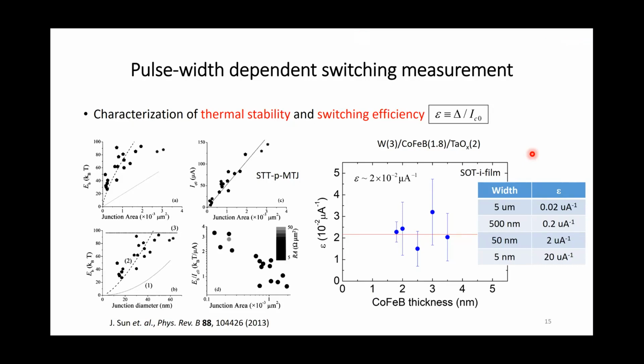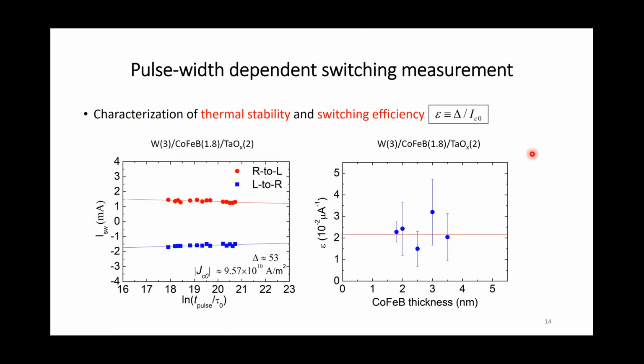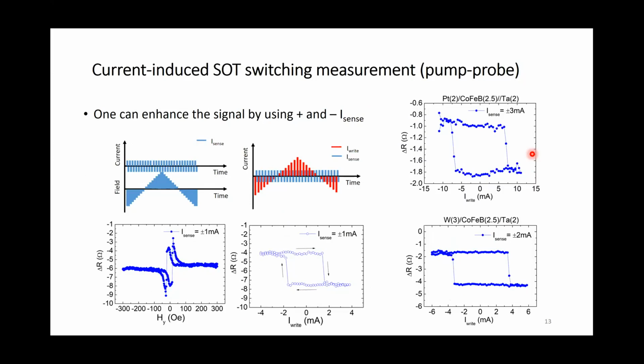Hi, Professor Pai. Great talk. I have a question. For the in-plane magnetization switching, there is an effect of the Oersted field also. I was wondering if you have estimated the Oersted field generated by the current in these tungsten and platinum-based devices.